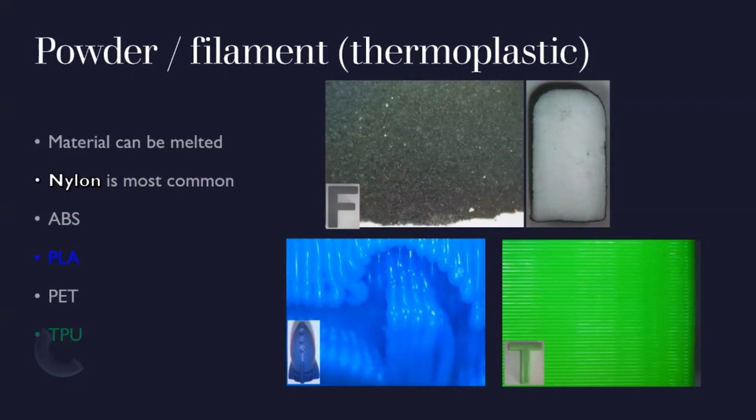This object was printed using the SLS technique, although nylon can also be in filament form and be extruded. Under the microscope, you can see the object was not made in filament form and used under the fused filament fabrication method, as the surface of the letter is made of many, many fine grains adhered to each other.